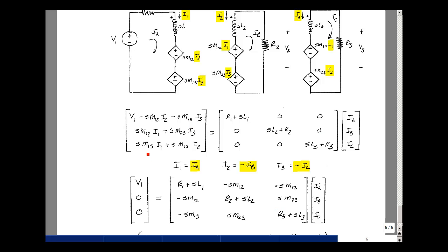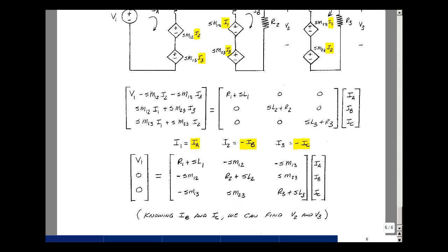And then lastly, bringing this on this side of the equation, we get a negative of that term, and then IA equals I1, be in column 1, and then this second term here will be SM23 times I2, but I2 is a minus I sub B. So when we bring it on this side of the equation, it becomes negative, and then another negative, so I get a positive sign. So now I have my mesh equations, and I can solve for any or all the mesh currents. And this is supplemental problem 15.5.